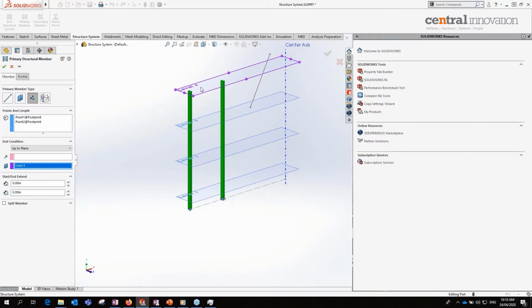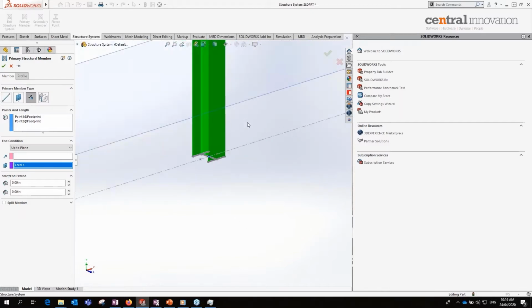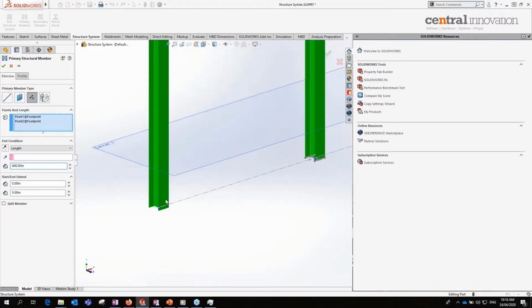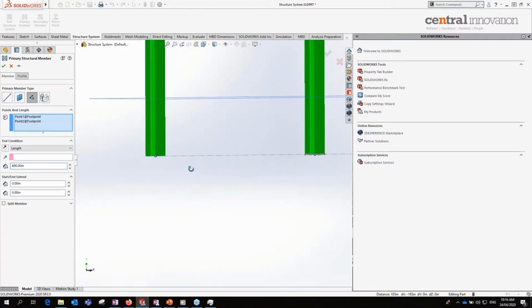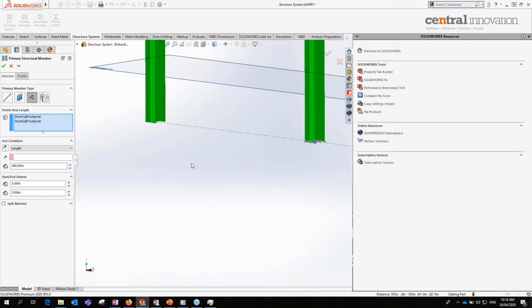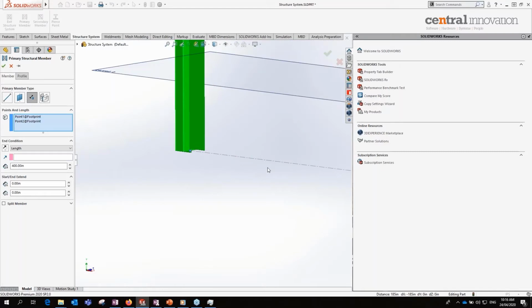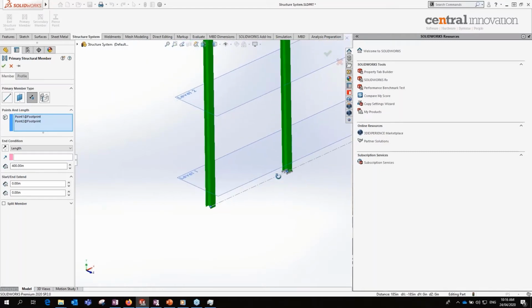For any of these conditions, you usually have an option here to define a direction. Because usually the direction is perpendicular to the sketch plane of the point. If you remember, guys, when we started here with the option length, we defined the length to be 500 or 400. But why is the length in this direction? Because usually the extrusion or the member will be perpendicular to the sketch plane. So the point was sketched in a 2D sketch in the bottom plane or the top plane.